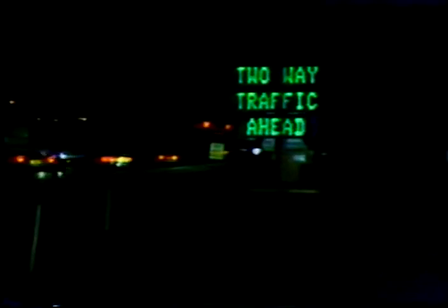Changeable message signs, when required, should be stationed at the planned locations. Drivers should have enough time to read the entire message series at least twice before they pass the device. And when warning lights or other devices are used to delineate concrete barriers, you have to check the spacing of those devices. The spacing should be according to plan.